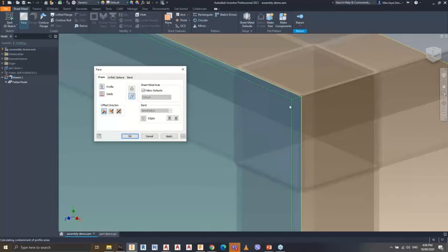But the big question is, what is the difference between standard .IPT and sheet metal design? Okay, pag standard .IPT, you can create different thickness on your model. Kapag sheet metal design, uniform ang thickness kasi nakabase ka saan? Sa sheet metal defaults kung anong material yung gagamitin mo na sheet metal. Are we clear? Okay, let's continue on this.